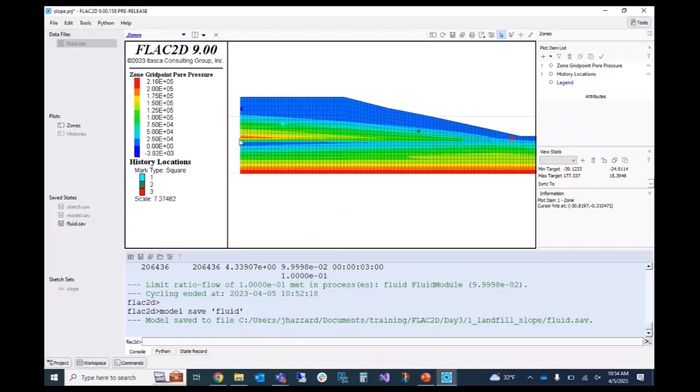We're forcing the pore pressure to be 0 to, or the head to be 0 to 19 on the left-hand side here, above that layer. What I was going to say is if you ran it forever, then it would bleed through this layer and everything would equilibrate, but that's not actually true because of the fact that we're forcing this boundary condition on the left-hand side.